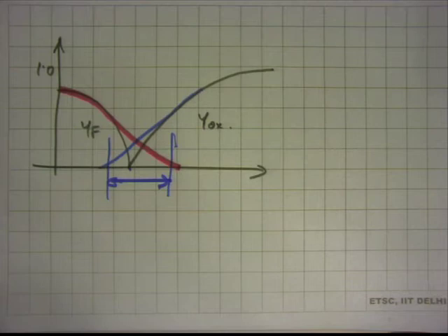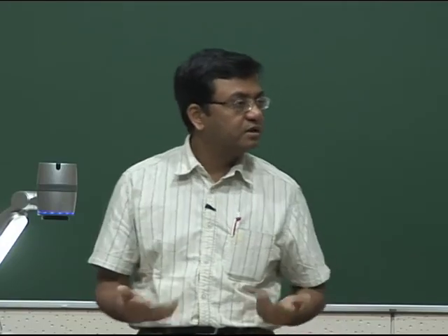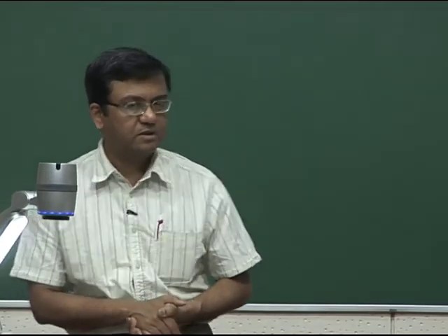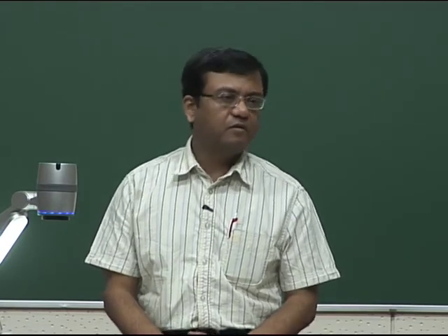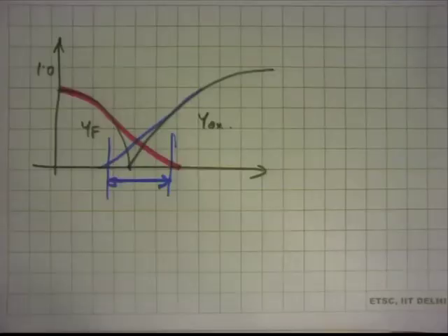So again, coming back to what we are doing, what I told you yesterday, that we are studying laminar jet flames, laminar jet diffusion flames, non-premixed flames. What is our objective? Our objective is to get all these profiles. One of our objectives. We want to get temperature as a function of r and x, then all velocities, if you have velocities vx and vr as function of r and x, and then these mass fractions. At least 3 mass fractions we have in mind: y fuel, y oxidizer, and y products as function of r and x. Okay, so that's one objective.